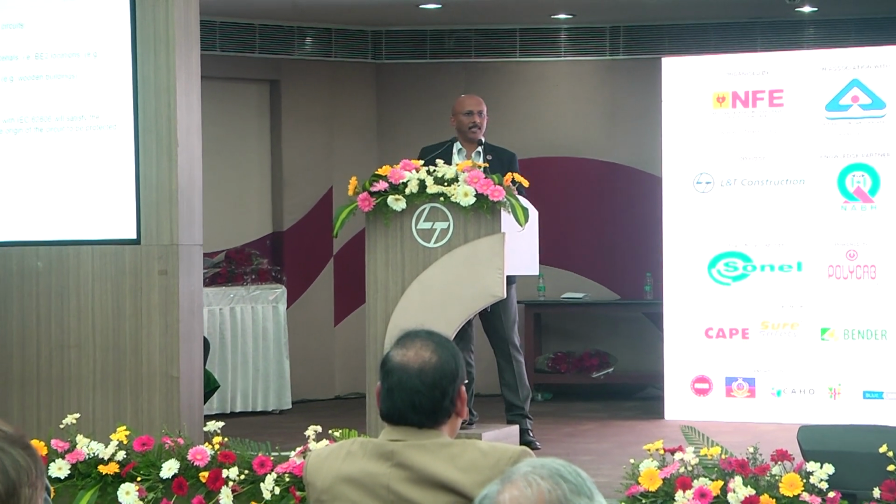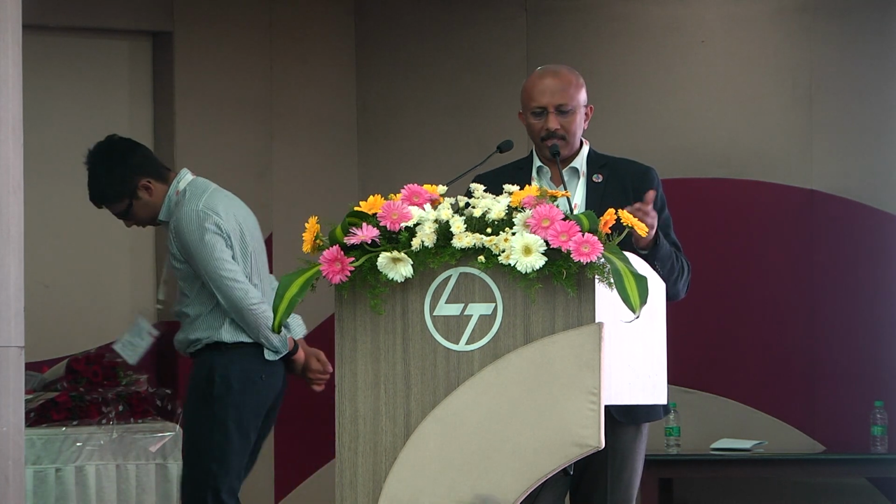There is a device called an Arc Flash Detection Device, because in a good electrical installation, where overcurrent protected, earth fault protected, and all the conventional safety measures are already there, now if there is an arcing, either series or parallel arcing, there is a chance of fire, and these devices come to the rescue. These are called AFDD. This is included in Part 1. I will just show you where it is included.